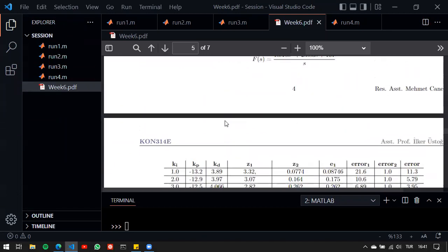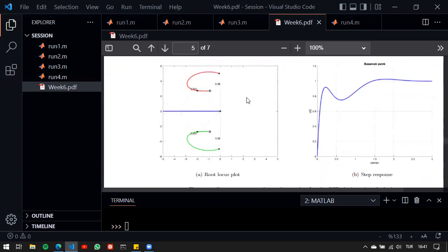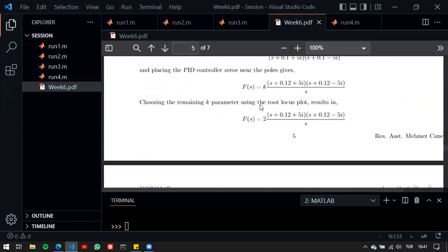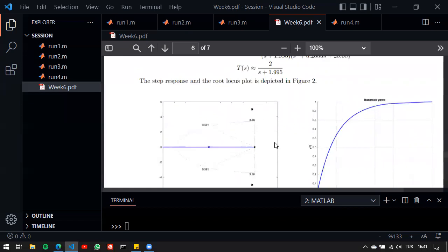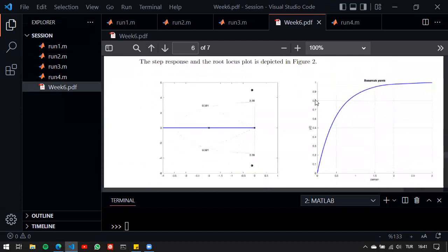And then with the solution here, I've also provided the zeros and all the stuff that might be filled into the table. But the important part here is that we have such a result, and it might be possible to opt for direct and exact pole zero cancellation. But both this one and this one correspond to a certain bandpass filter. At this point, if you have an exact pole zero cancellation, you don't really see the effect of the bandpass filter. But if you have this, then it has a certain quality factor and a certain bandwidth to it. So that affects the system's response in closed loop.